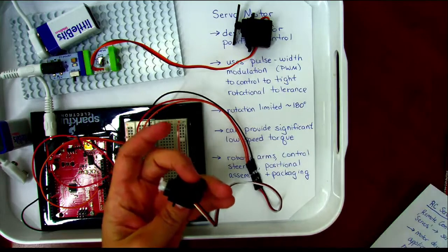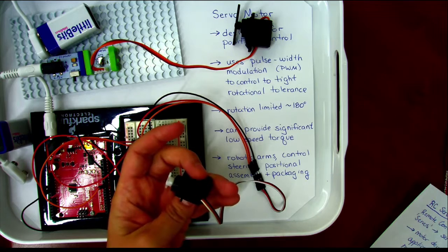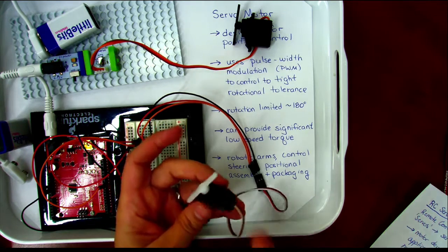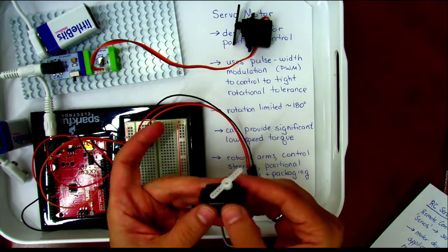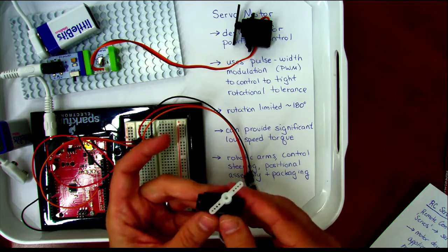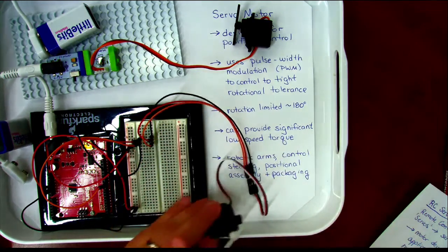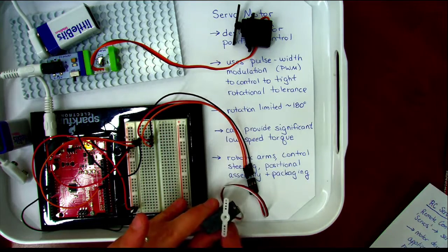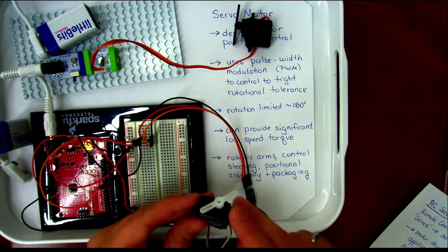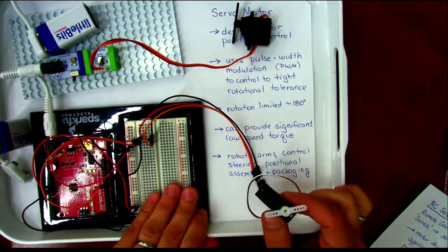One is for the power supply, one is for the ground, and then one is for the shaft positioning control that's sending that pulse width modulation to tell it. Inside of here, there's actually another little motor that's geared down to do this very, very slow control. So it has a little feedback device in this box. There's a lot packed into this little guy. That's why it takes some size to him. And again, you need something to tell it the pulse width modulation.